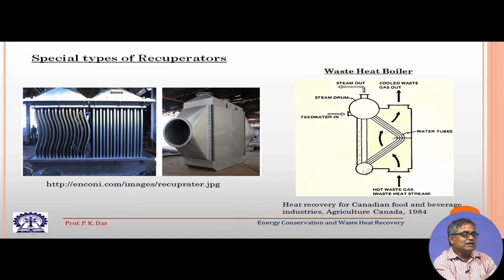These are the riser tubes of the boiler. Here the steam generation will take place, and then it will go to the steam drum. Steam will be taken out. Here one can give the feed water, and this is the downcomer through which cold water will come out.